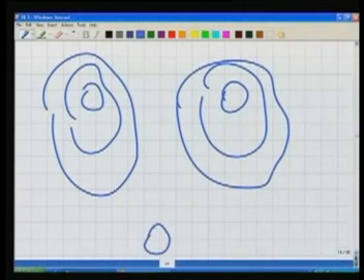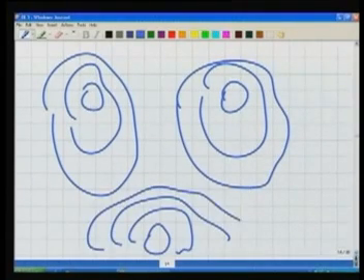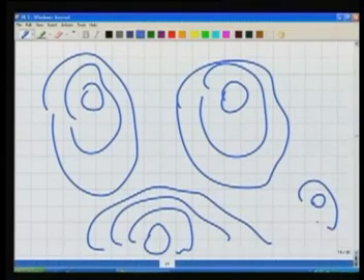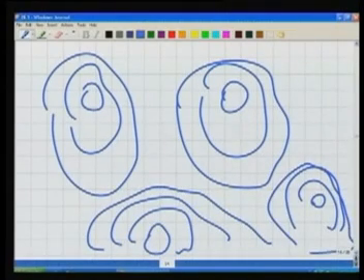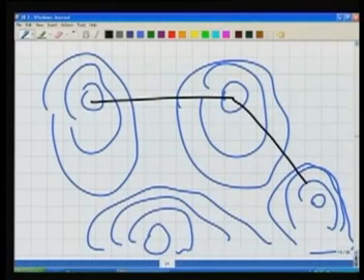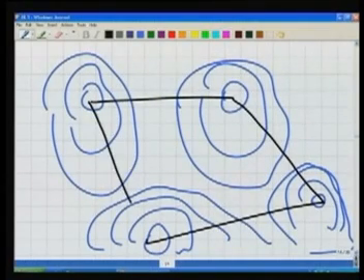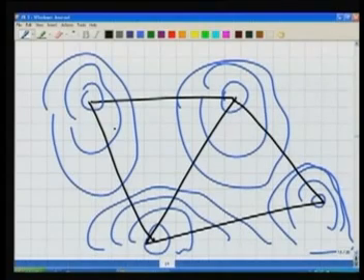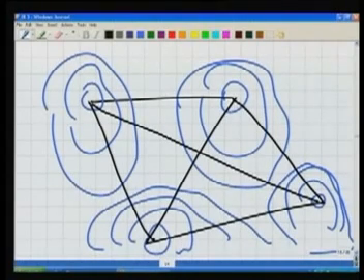It's a hilly terrain and at some point here we want to map this. So what I can do, I would prefer to establish a braced quadrilateral here in between these hilltops, and then somehow by a base extension method I will measure all the internal angles.